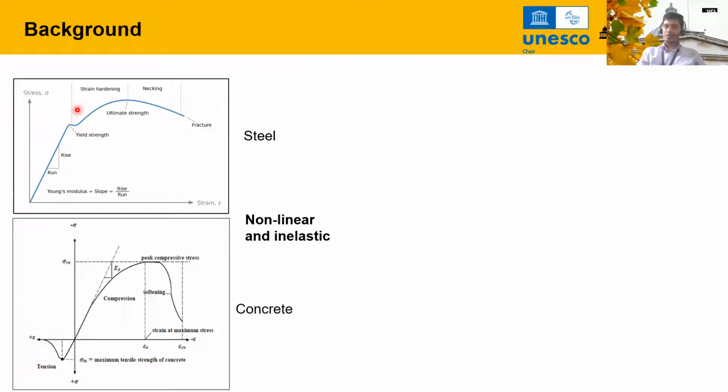For example, in designing our structures, if we design within this realistic range, then our structure becomes weak, or it has low seismic capacity. So that's not good. And if we design it with the assumption of linear behavior for higher loads, then that's not also good, because we are overestimating its strength, because its strength goes like this, not like this. So this tells us that the linear elastic analysis is not appropriate and does not give us reliable results.